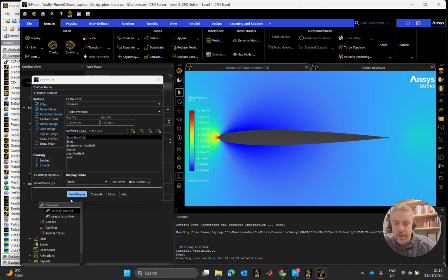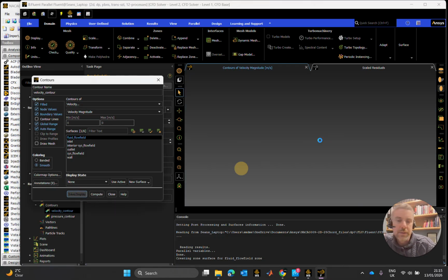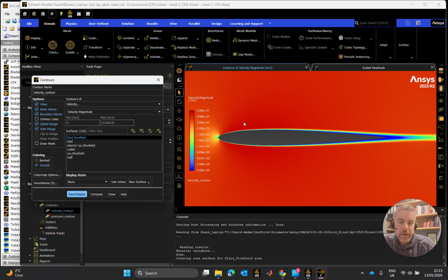Now, it's important there as well. If you ever get quizzed on it, I don't think you ever will be as such, but just that you'll often hear that it is this negative pressure that gives lift. Indeed, if the airfoil is so orientated to give lift, or it's that low pressure here that gives downforce if the airfoil is inverted and orientated to give downforce. But that's not strictly true. That's only part of the story.